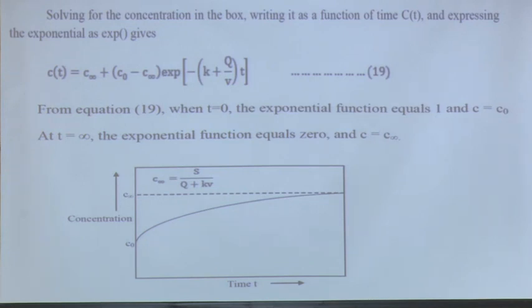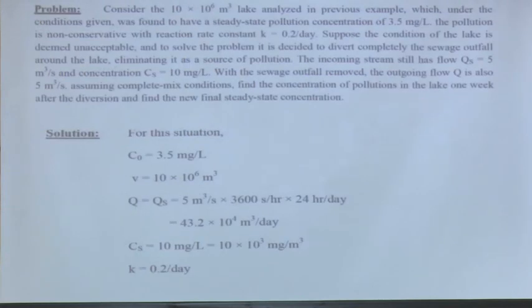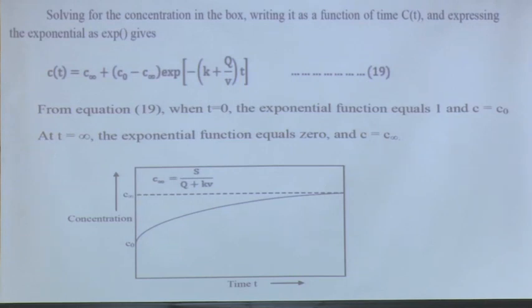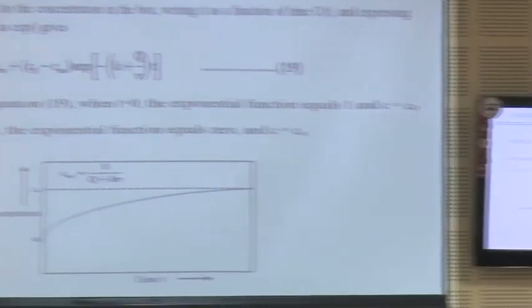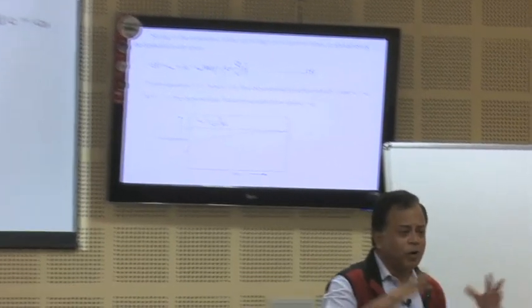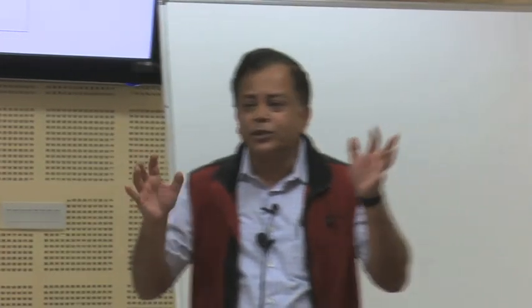So, let us solve one problem by applying this. Do not worry, I am giving the solution, just for practice. Now, this is a very interesting one. In the previous example, we had a flowing river, and there I have a lake, and there I am discharging some waste material, and I want to test how the concentration varies with time, up to the equilibrium concentration.